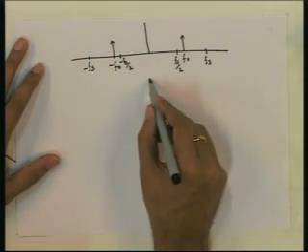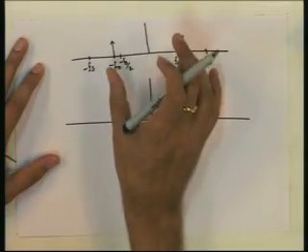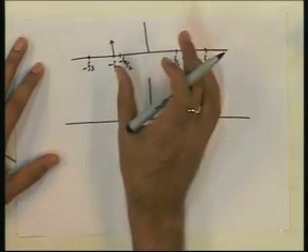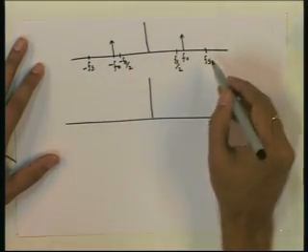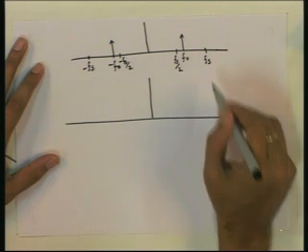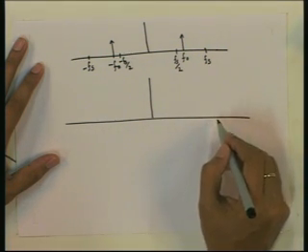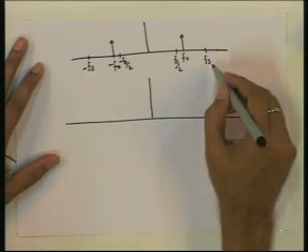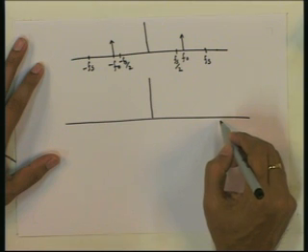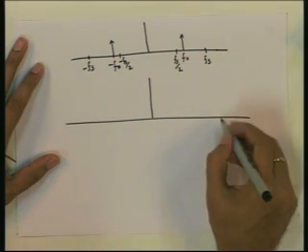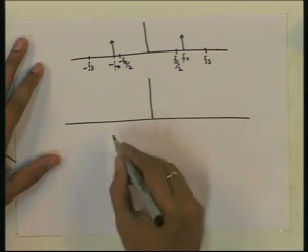Now, when we discretize the signal, the DTFT will look like this. We will have this shifted to multiples of Fs and then added, and of course, the frequency will be scaled so that Fs will be mapped to 2 pi. So, this 2 pi is the angular frequency actually. So, Fs will be mapped to 1 if we normalize the frequency in DTFT.